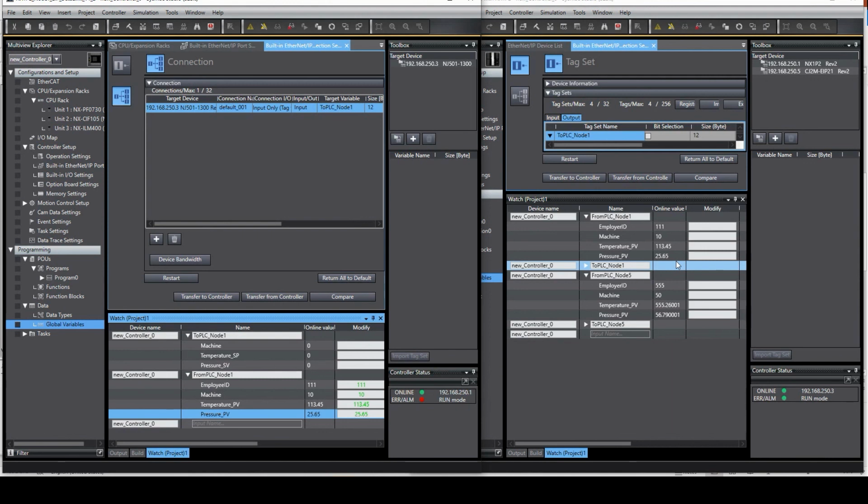As you can see, this is how you set up the Ethernet IP communication to gather data from the slave PLC to the master PLC. And the slave can be a C-series PLC, in this case CJ2M CPU33, or any NX PLC or machine automation controller, back to the machine automation controller NX or NJ series PLC.